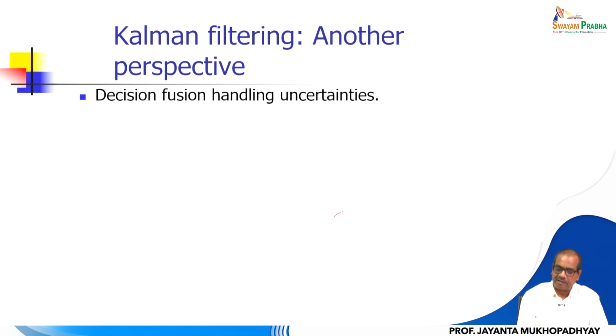One is due to prediction, you have a position, and again due to measurement you can try to make another kind of decision. So, how to fuse both of them gives you the ultimate update operation using the Kalman gain. So, we will see that this kind of modeling of handling uncertainties could be well explained using this framework.